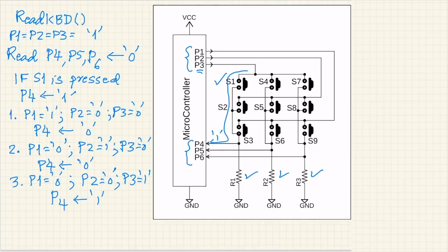So what it is going to do is it is going to wait, but before that, when you press a switch, as we have mentioned, there is a bouncing on the switch, so it has to debounce that switch. So it's going to call a delay subroutine for 1 millisecond. After that, it's going to wait for S1 to be released.